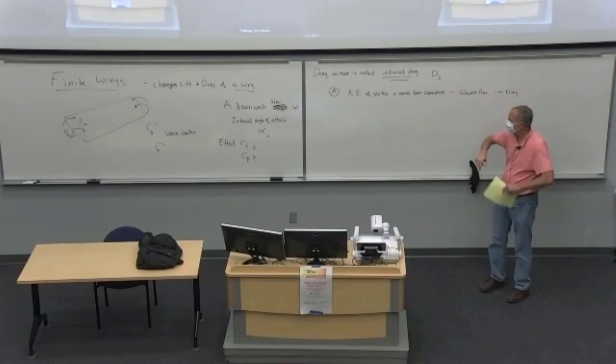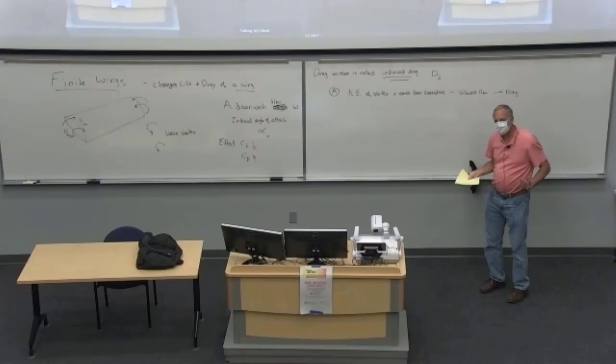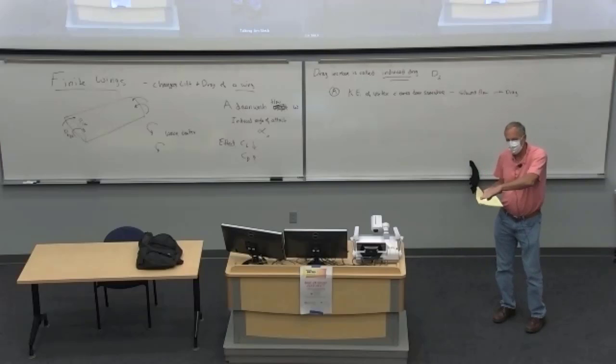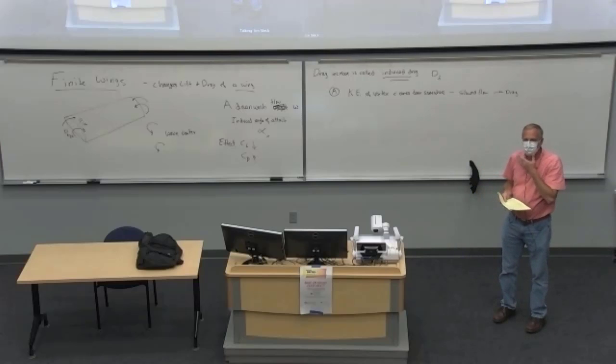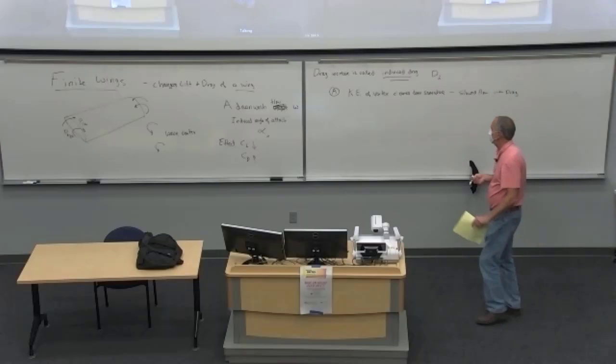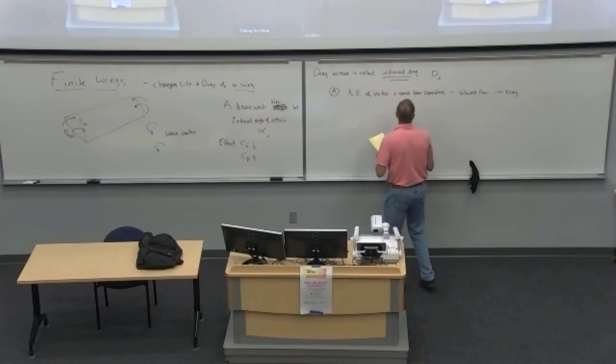Because the flow turns into this swirling flow instead of going smoothly over the airfoil. And that energy goes from the smooth flow into the vortex, and because the wing pushes on the air to cause that, you get an equal and opposite reaction on the wing from the air, creating drag. So the kinetic energy comes from somewhere, you get drag.